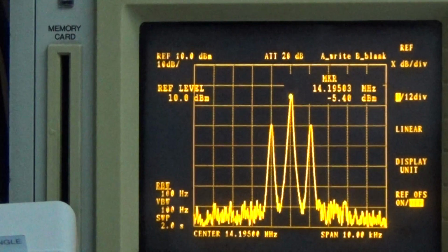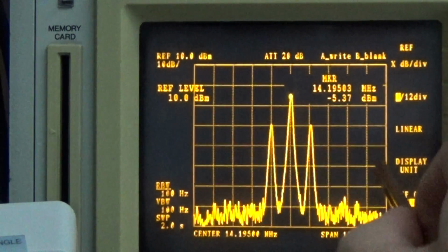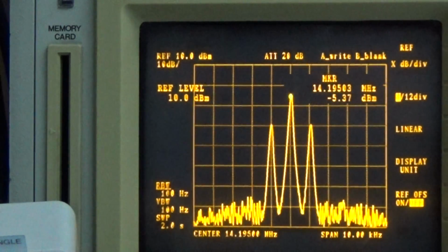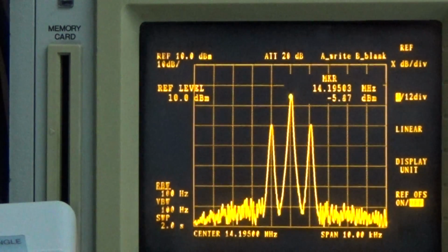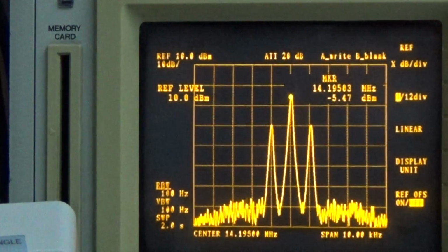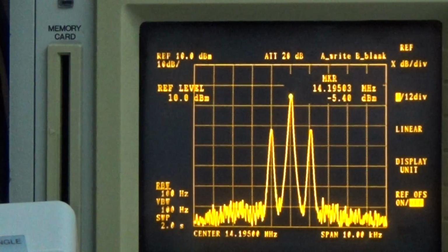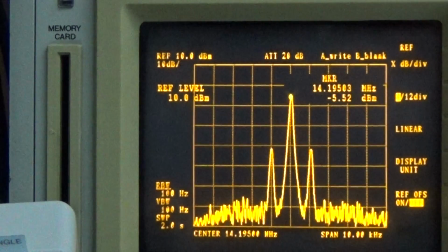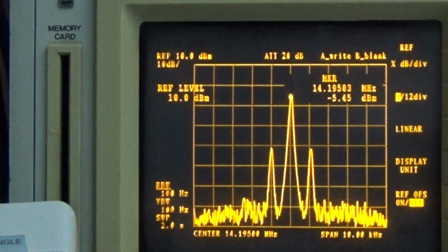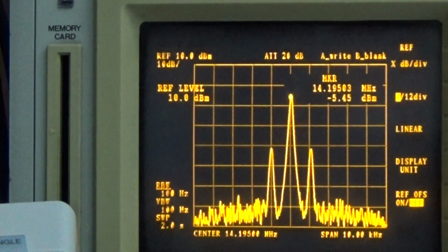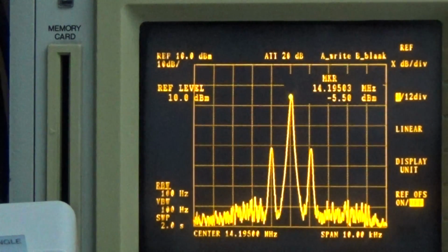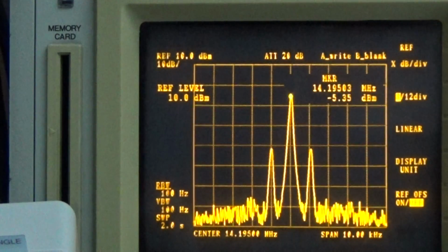So it takes a while until the information is present here on our spectrum analyzer. And if I decrease the audio level, you see now our sidebands are dropping. So that is nothing else than the information about our audio volume gain, if you like.